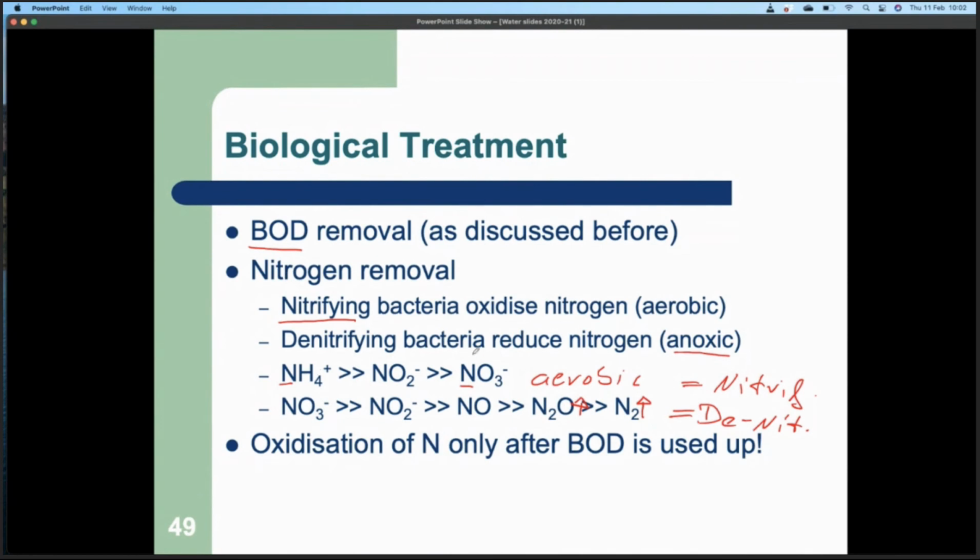So really you have to measure ammonia and nitrate. And if you have no ammonia and no nitrate, then you might say, oh yeah, I have achieved my aim, but you may also have generated nitrous oxide. So what I'm saying is that to fully understand what happens, one should measure ammonia, nitrate, and nitrous oxide emissions, because you want to avoid these.